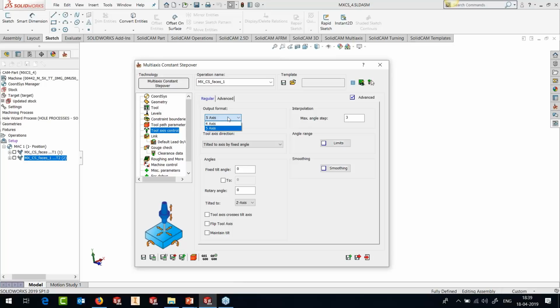But for people with SP2 who have downloaded it, the 3-axis toolpath still exists there. You can experiment with this toolpath engine on your 3-axis paths, cut them, and let us know the results, because we have got consistently very good results with this particular toolpath.